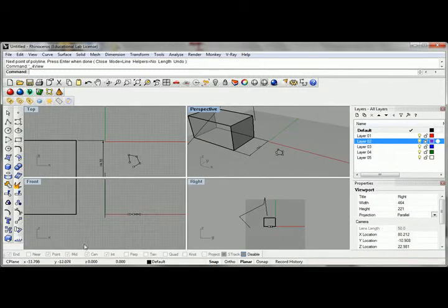Object snapping, O-snapping, is really handy when you actually start to build geometry. You can snap to the endpoints, you can snap to whatever's near, though it's generally less functional if you're trying to do something precise. Points, the middle of something, the center of something. If you have an object, it'll try and calculate the centroid. The intercept, perpendicular, you get it.